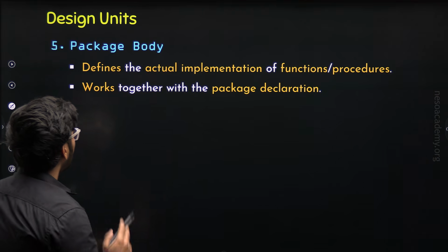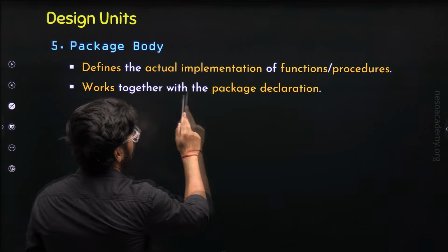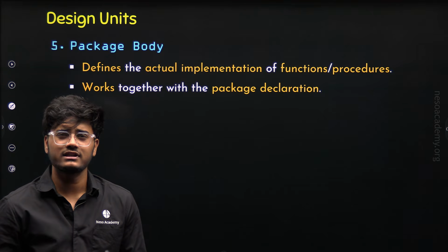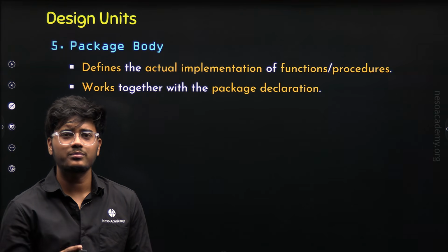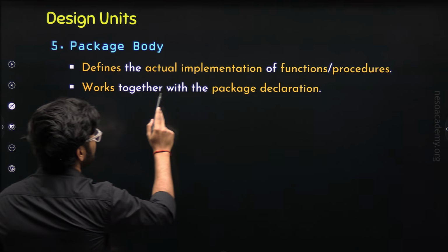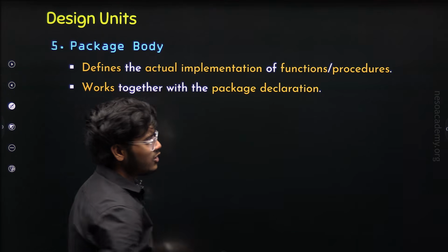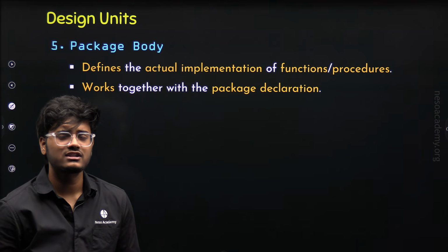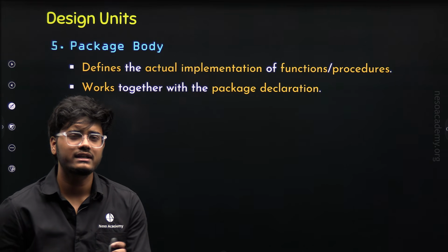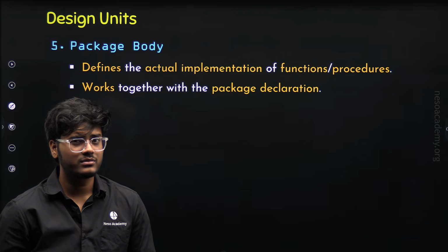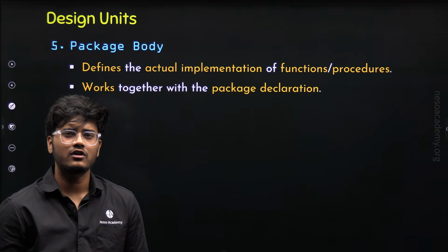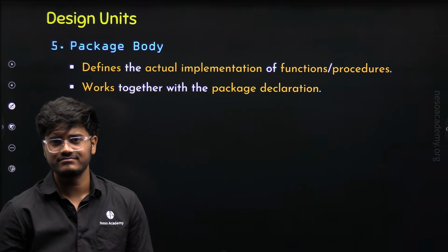Next point, package body works together with the package declaration. Now, package declaration alone is not enough. We need a proper actual logic. So, package body works together with the package declaration. Overall, package declaration tells what is available to use, and package body tells how it actually works. But remember, packages are mainly used for reusability and not for defining hardware directly.